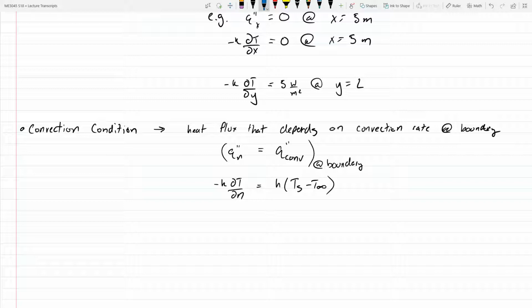What's going to occur is that as the thermal energy is dissipated away by convection, your surface temperature is going to drop, right? You're going to get this convective cooling, which cools down the edges of the block. That's going to create a temperature non-uniformity inside of the block. So the temperature of the edges will be lower than the temperature at the center.